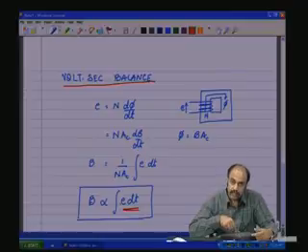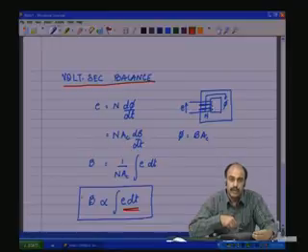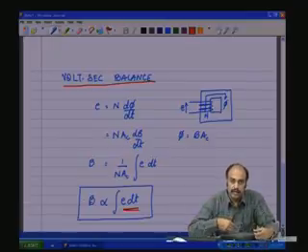So, if this value, the integral of E dt, is continuously increasing, then a time approaches when the value goes beyond the flux density permitted for the core, and the core will saturate, it loses its electromagnetic property and it will just be a plain short circuit.